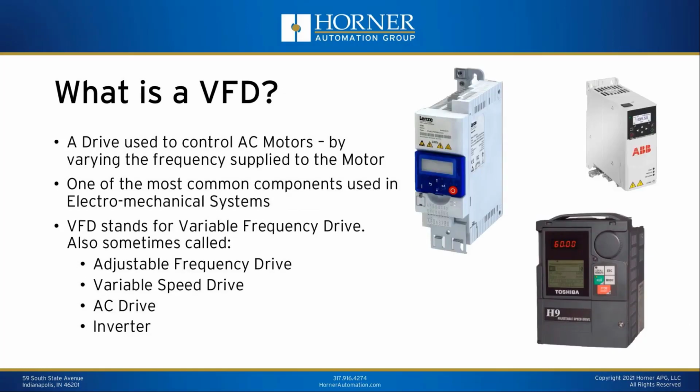A VFD is a general term. It stands for variable frequency drive. This is a type of drive that's used to control AC motors by varying the frequency supplied to the motor. It's certainly one of the most common components used in electromechanical systems out there. And VFDs are often called other things. So it's not always variable frequency drive. They're sometimes called adjustable frequency drives or adjustable speed drives, variable speed drives, AC drives, inverters, a lot of different names for basically the same thing. Okay, so that's just a quick introduction of what we're talking about with an OCS and a VFD.